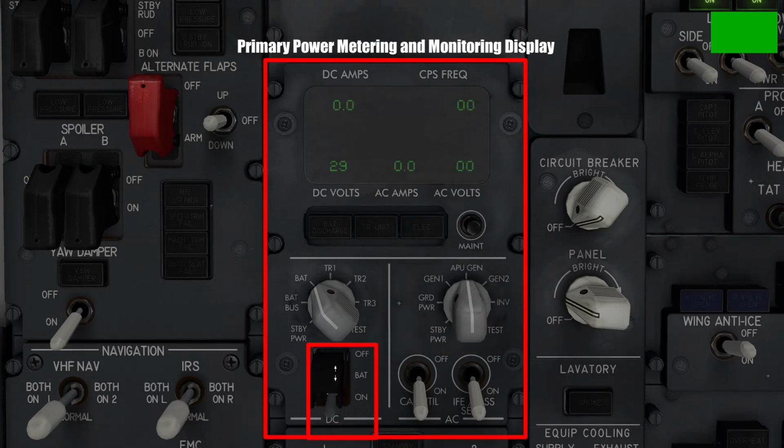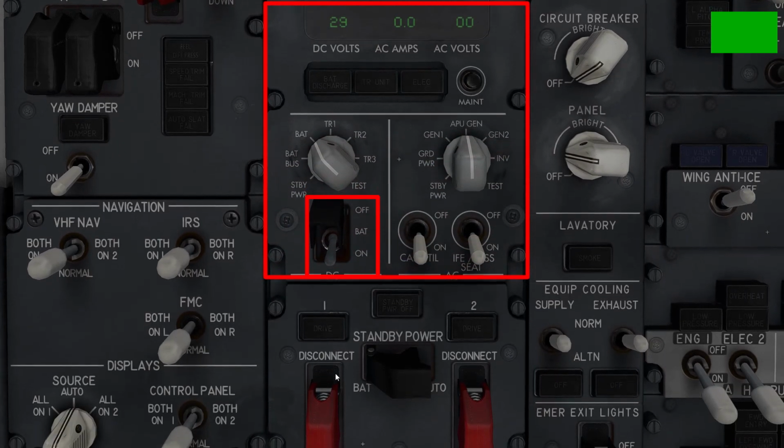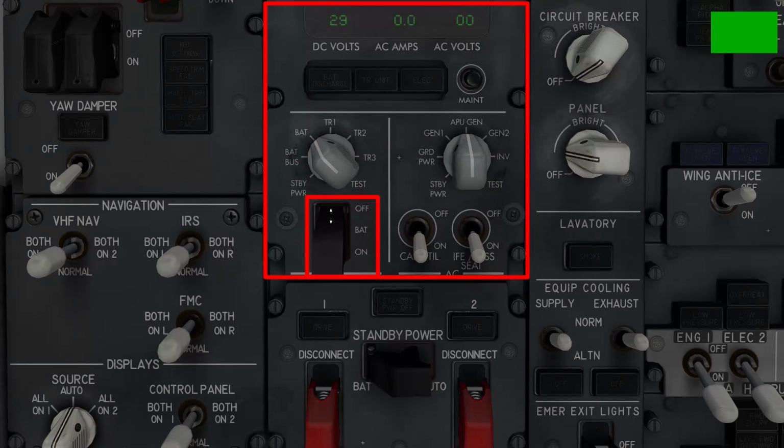Coming underneath, we have a black guarded cover under which is the primary battery switch. Shutting this cover down automatically switches the battery on, and this is normally the first button or switch to be manipulated by pilots when starting the aircraft from a cold and dark state.